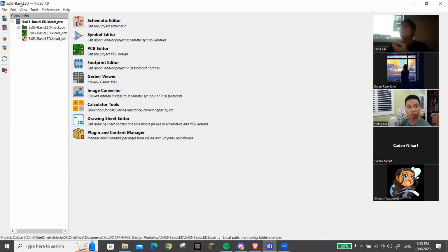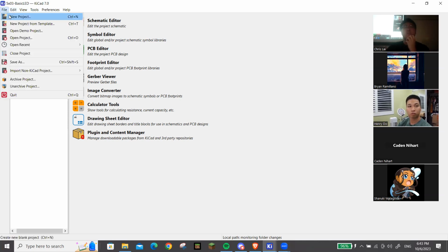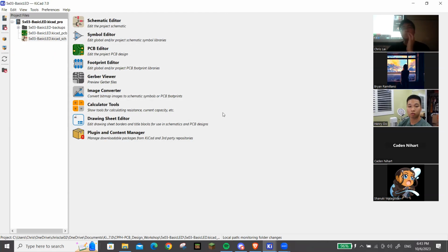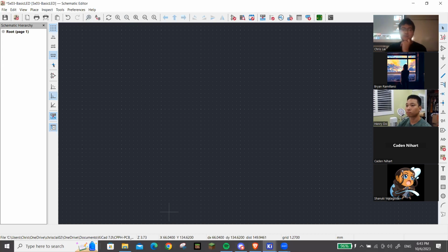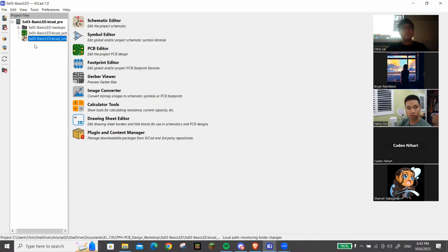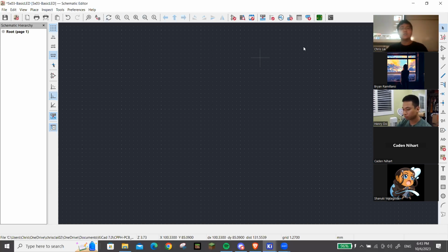So we're going to create a new project. In this case, I'm going to name my basic LED as it's the circuit I created. Just go to File and click on New Project and name your project in whatever folder you want to save this in. All right, that's the first step. Should be pretty simple. Once you have that finished, we are going to go with the first step of PCB production, which is to make the circuit schematic. So you're going to double click on this schematic icon in the main menu, which is this one down there. And that should open up a page with this sort of dotted structure on it.